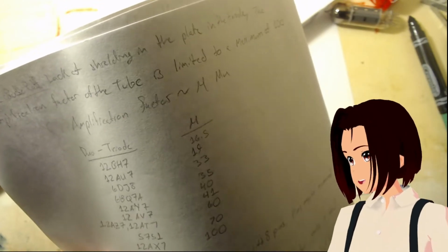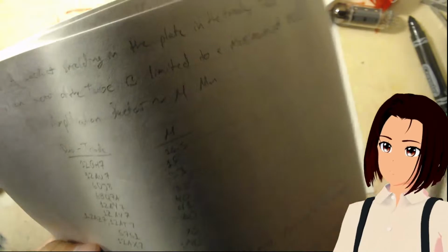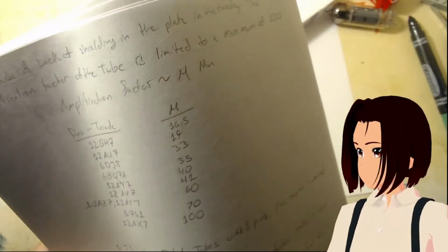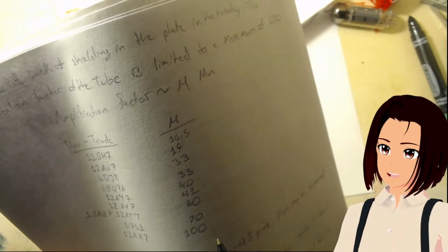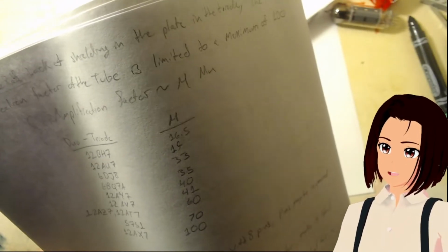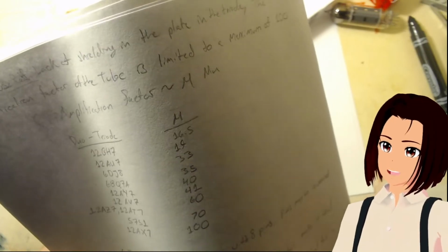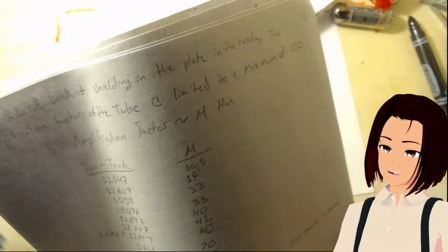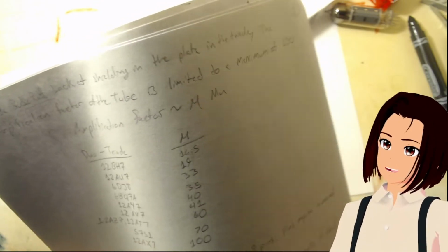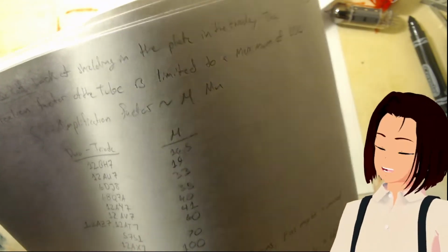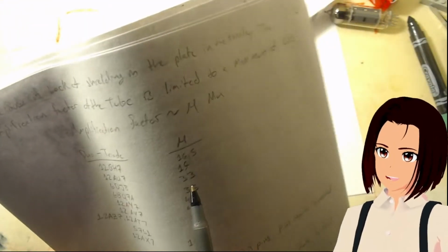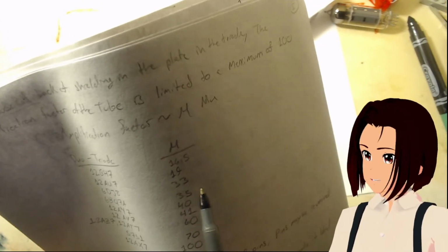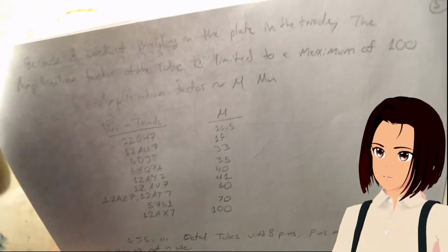But some of these tubes are good for phase inversion, because we don't necessarily need that high amplification factor. The high amplification factor is useful if we're running high voltage on it. But for some of these lower ones, you don't need as high voltage, and especially for a phase inverter. You could probably use maybe a 12AU7. I don't know if that's the right amplification factor for an AU7. I might need to check my sources again.